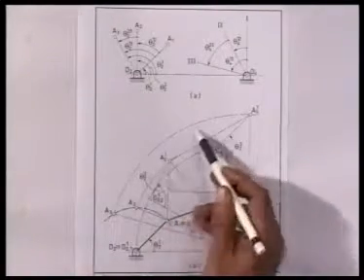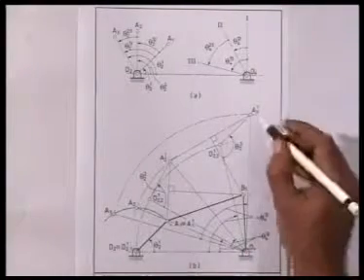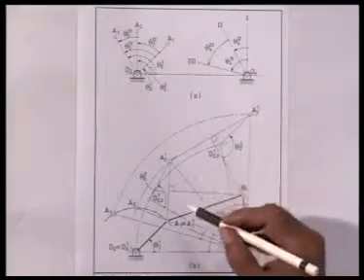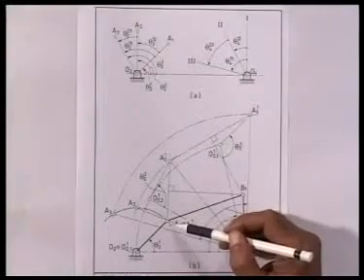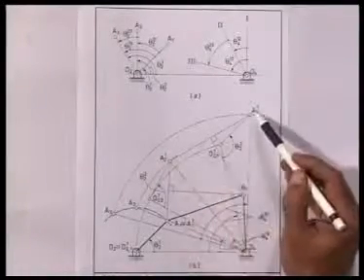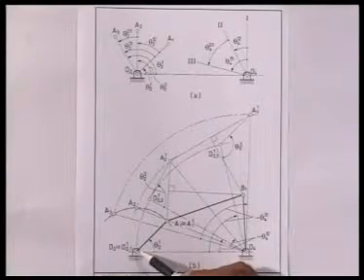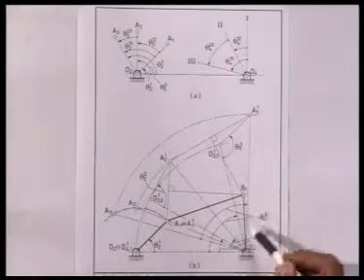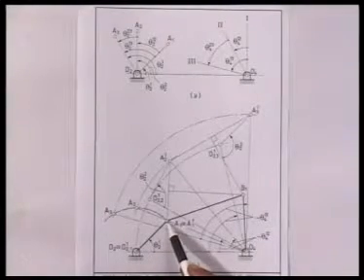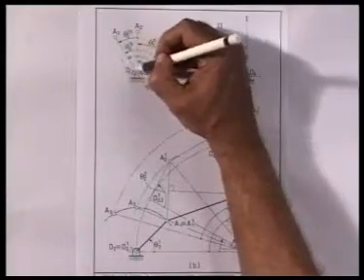So rotating O4 A3 about O4 through minus theta 4 1 3, I located A3 1. Then the center of the circle passing through these three inverted positions of A, namely A1 which is A1 1, A2 1 and A3 1, I located B1, and the design was complete as O2 A1 B1 O4. So with such an arbitrary choice of A1, if I had one more pair of coordinated movements,